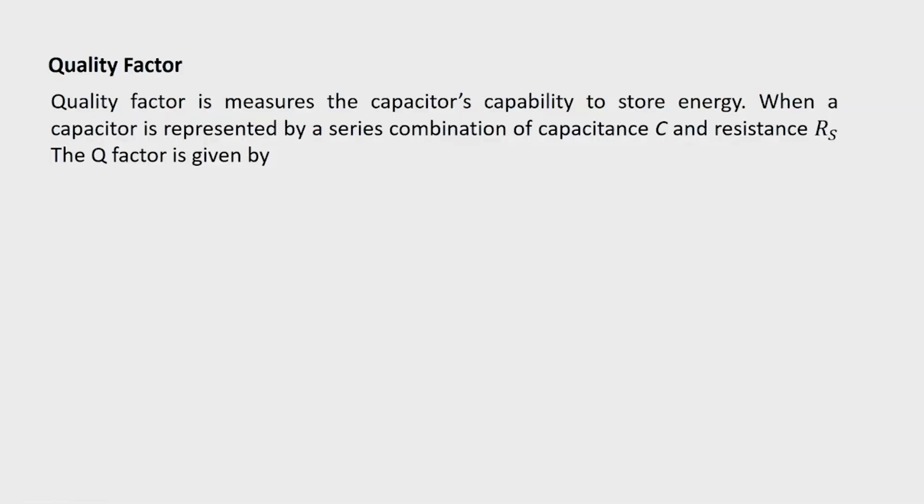Quality factor, as already mentioned, is a measure of a capacitor's capability to store energy, and when a capacitor is represented by a series combination of capacitance C and a series resistance Rs, we can write the quality factor Q to be equal to 1 by 2 pi f C Rs. So, smaller the value of capacitance, higher will be the value of Q,